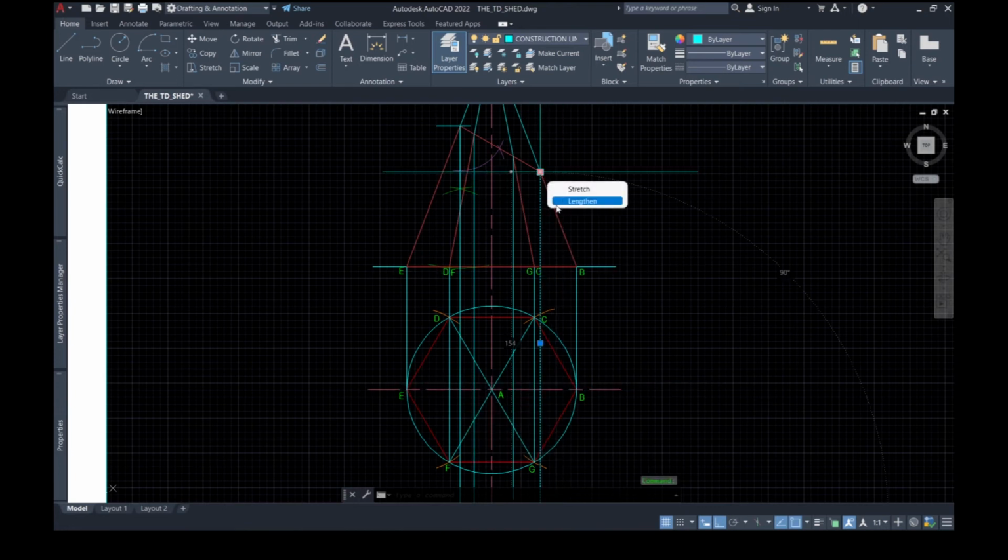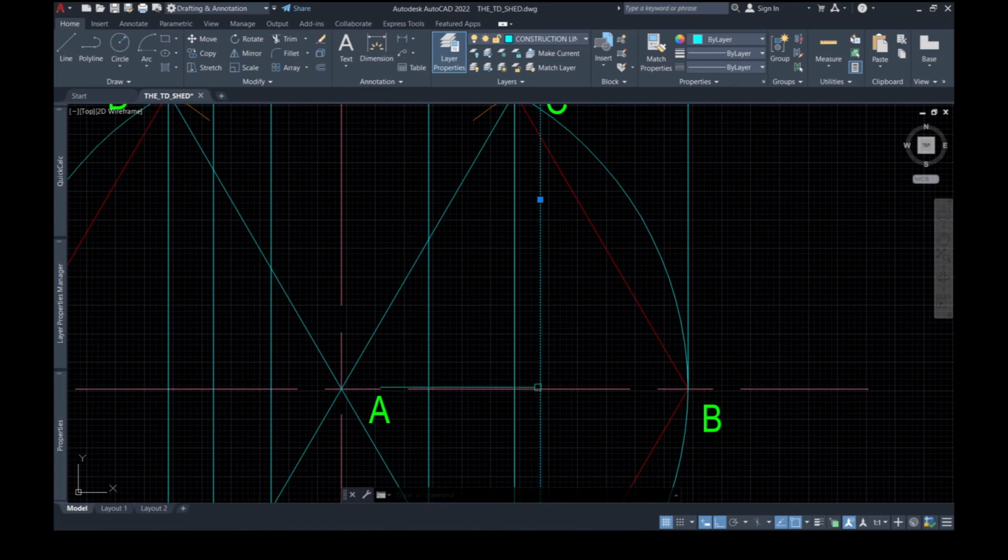This line here corresponds to the line at point B. So we go down to the plan and we look for the line that corresponds with point B. This would be the original center line. So this point right here would be our first point.